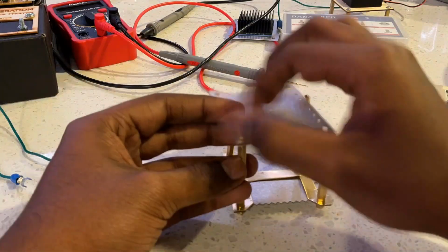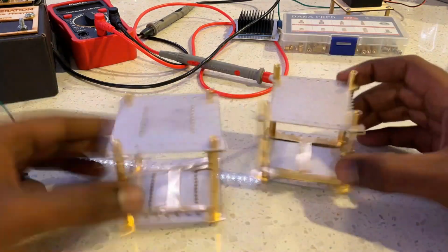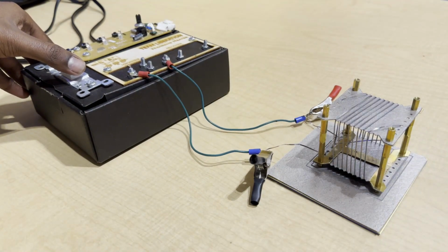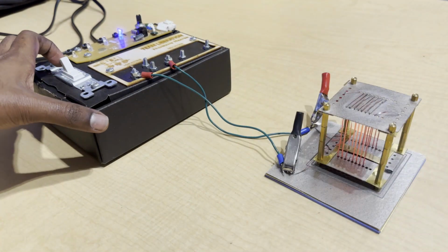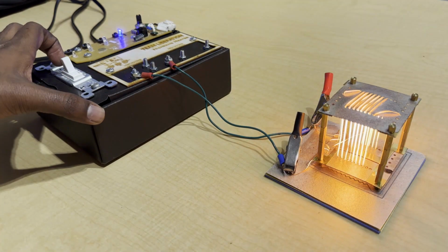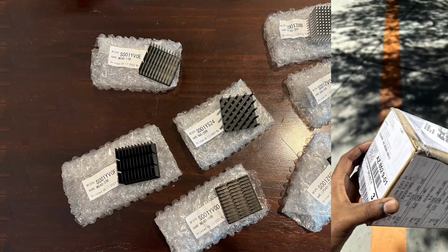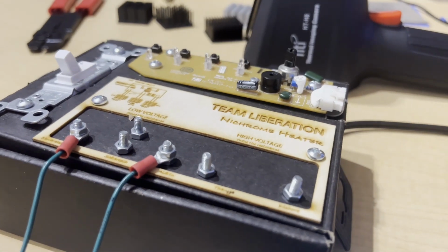It's much easier to wind in this configuration, and we also switched nichrome wire with nichrome tape, which had a firm structure, making winding it through the mica sheets easier. The test bed worked perfectly and surprisingly good in both the configurations. The only thing left to do was to get heatsinks to test the heating bed. And with that, we had everything to begin our experiment.